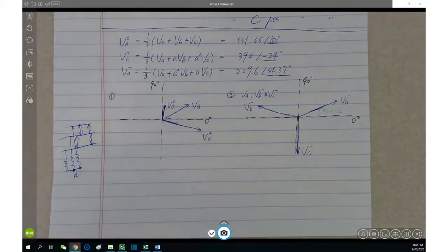But here, to your approximation, my expertise is not power analysis, actually. However, generally speaking, people calculating the real power only use the positive sequence. Negative sequence and zero sequence are generally very small. We extract those out and then use only positive sequence components to calculate the power in the system.